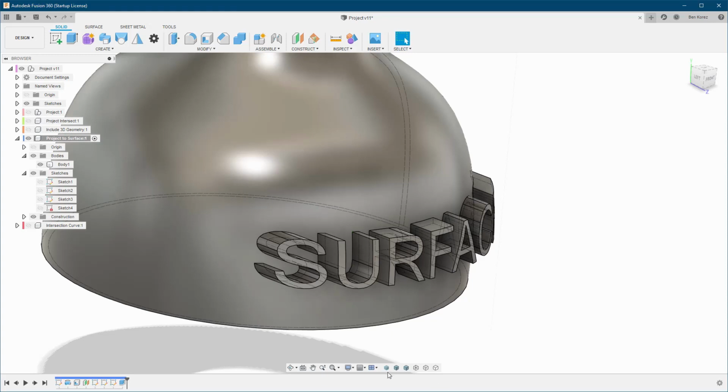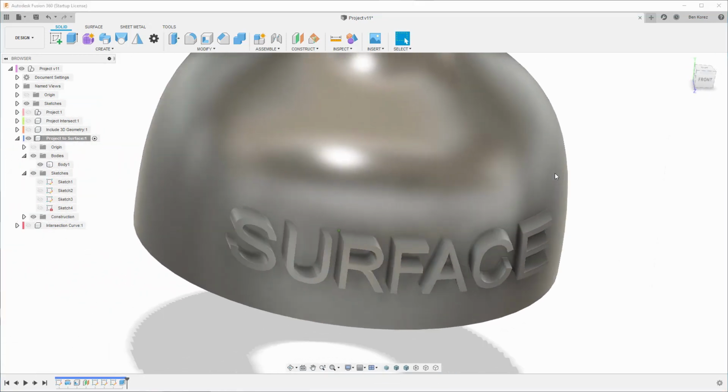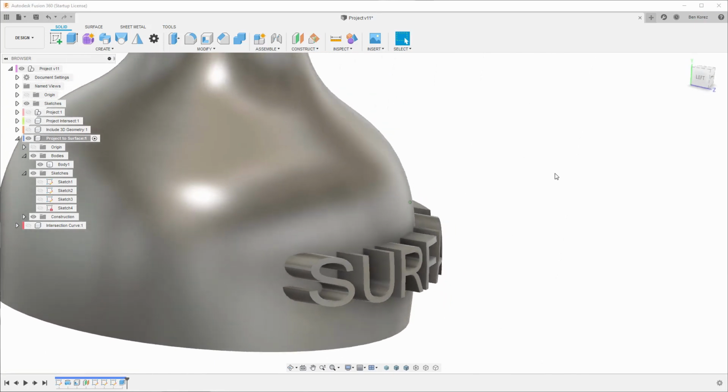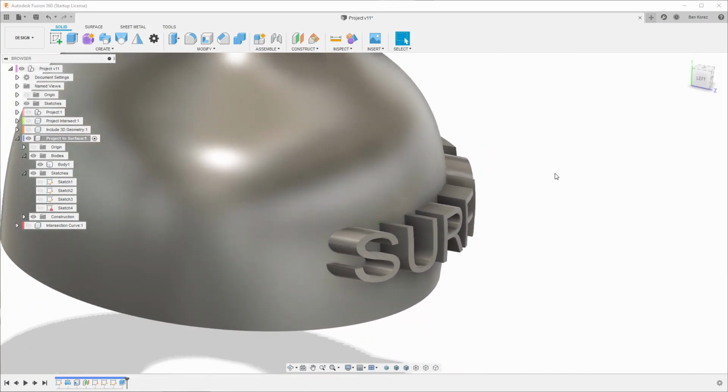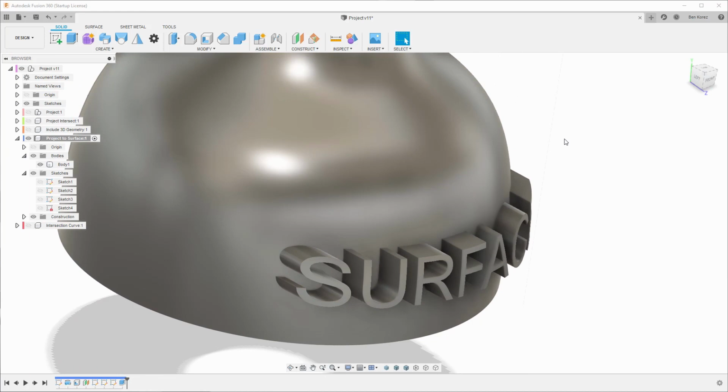And here we go. Let's change the view. It looks really, really nice. And then from here we can shape it, you can make it more round or whatever you want. Give it fillets. Now you understand how project to surface works and when not to use it. I would suggest you figure it out depending on the design intent. I will not use project to surface unless anything else I've tried didn't work. But again, it depends on the design intent.